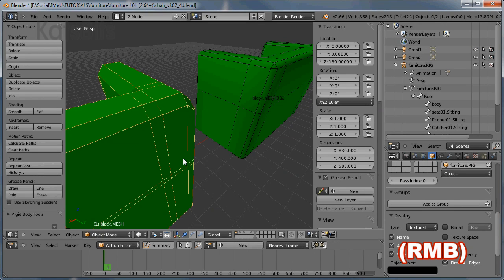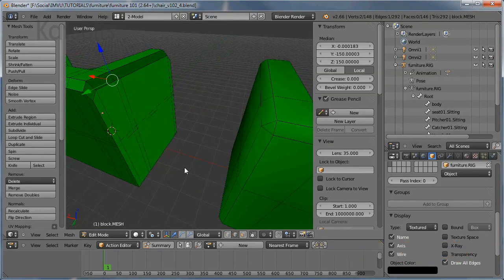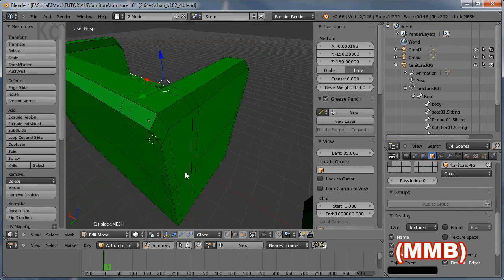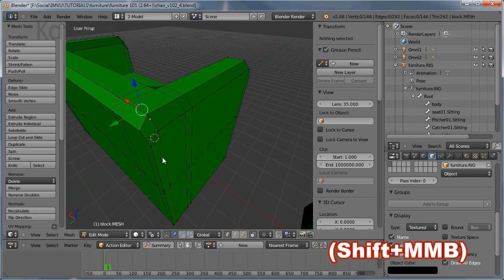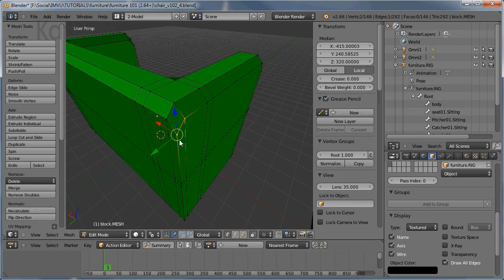So make sure the first mesh is selected again, tab into edit mode. There are two things that we can do here. This edge on the previous beveled version is beveled as a result of the tool, but on this version it's left perpendicular, because when we collapse these vertices together they create the rounded edge for us. So let's go around the mesh and do that first. So right click the vertex we need to merge to, then shift right mouse select the vertex that is being merged to the first selected vertex.